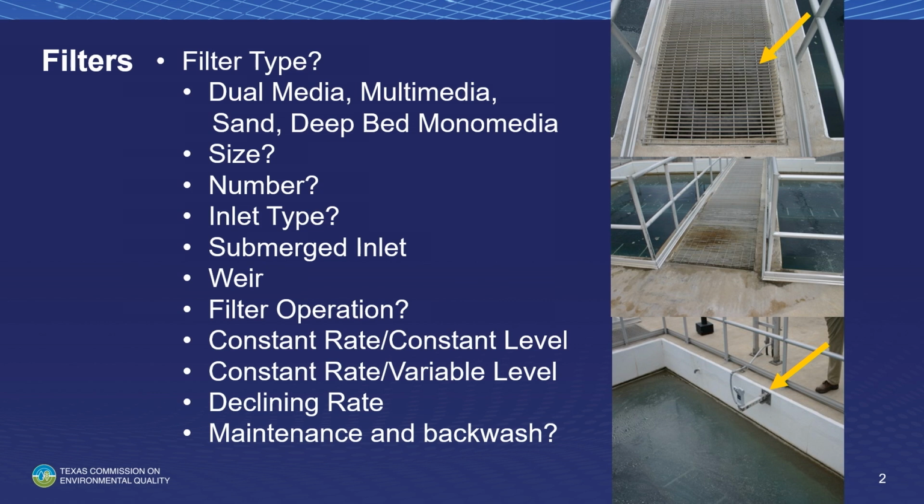Sample points, monitoring at the bottom of these filters. You know, you read the manufacturer's guidelines for how you're supposed to put the sample points for your turbidimeter on your CFE and your IFE. The whole point is to tap the pipes from the side, not from the bottom, because sedimentation happens in these pipes and it'll affect your turbidity readings.